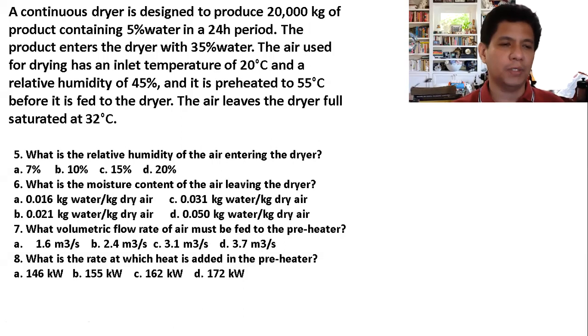Usually what's measured in the plant is volumetric flow rate, but for a heat balance, what's needed is mass flow rate. So that's the practical application of humid volume. Here you saw the use of C sub S, the humid heat, in the calculation of heat. So I hope you follow the solution.